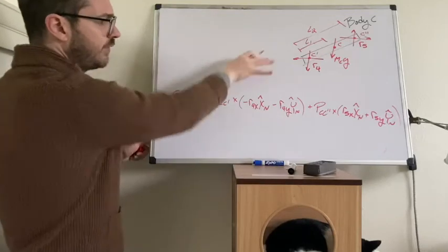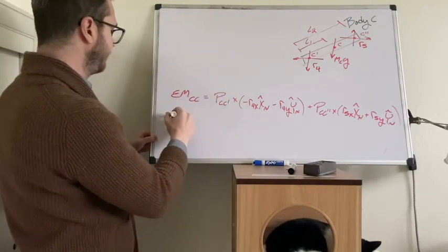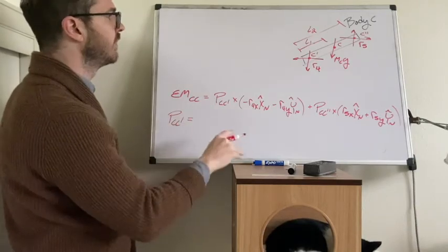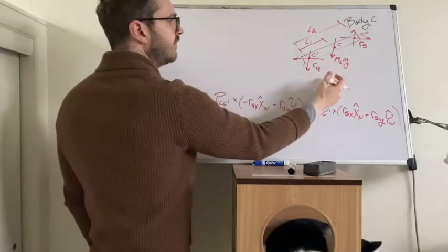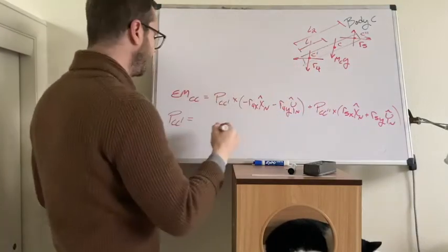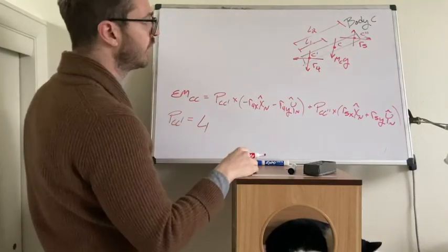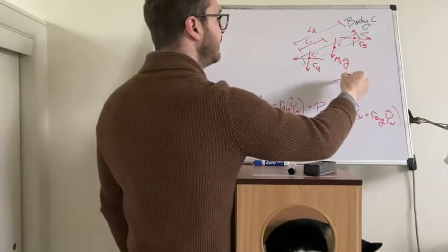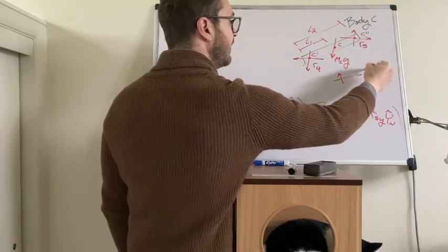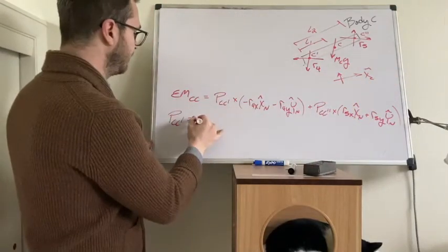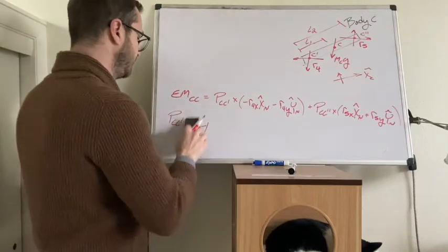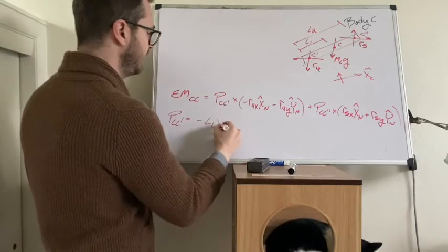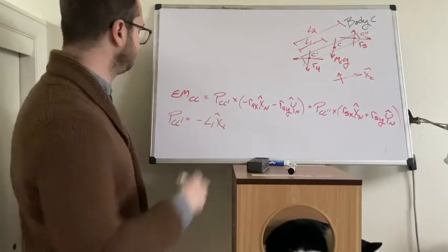Tell you what, before I rewrite the whole thing, I'm just going to write the position vectors here underneath. So here is P, position vector from C to C prime. C to C prime, center of mass down to the bottom left. We're going a distance L1, in the opposite direction. Go back and look at how we did position vectors. We called that direction XC. So this is minus L1 in the X hat C.